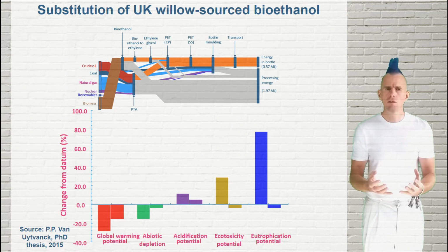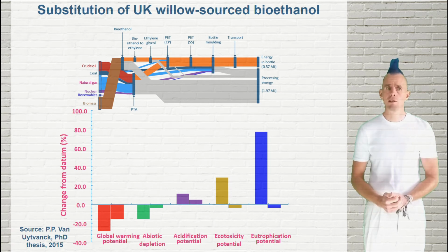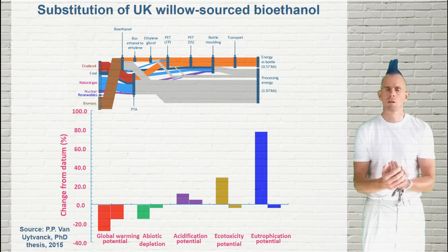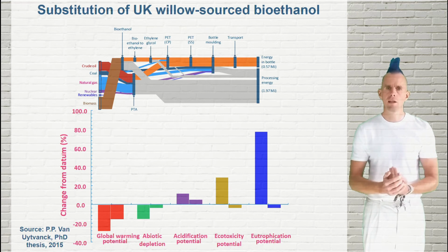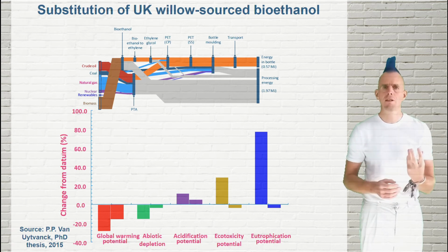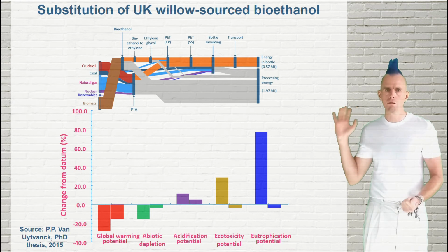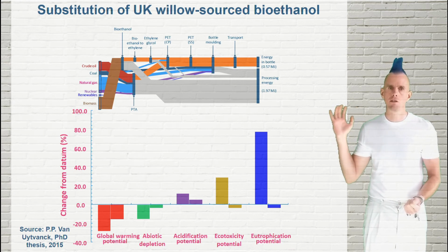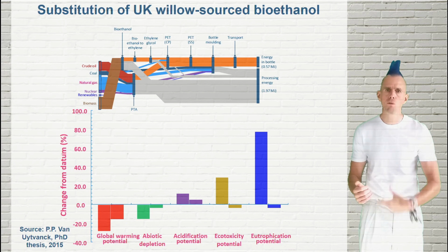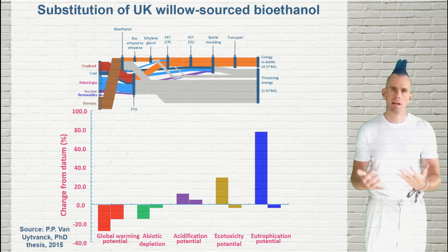If, however, you decide that a holistic picture is important, maybe domestically produced bioethanol from cellulosic feedstock is actually the way to go. You don't reduce global warming potential quite so much in the ethylene production, but overall we know that the focus needs to be on pure terephthalic acid production because that's the major energy user. And so maybe a smaller improvement in the environmental metrics for the ethylene step can be offset against far larger gains against a different processing step within the same value chain. It's a complex picture.